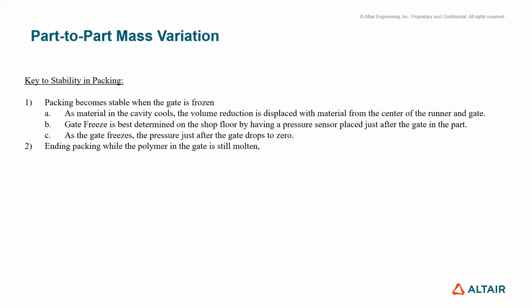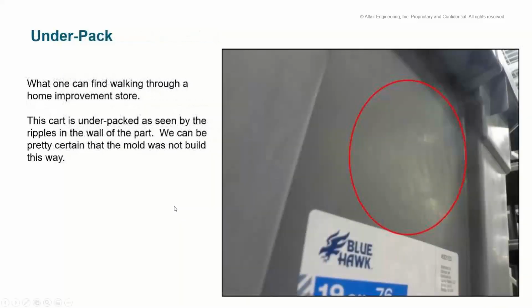If you have 2 times variation in thickness in different areas of your part, that's going to create excess shrink, warp, and cooling problems. So the more you can have the same thickness in all your nominal wall, ribs and things are going to be a little bit thinner, like 2/3 the thickness of the nominal wall. But again, you want them to be as even as possible. That's going to give you your best quality parts.